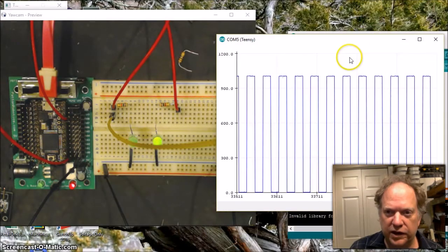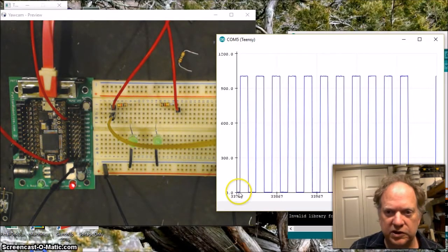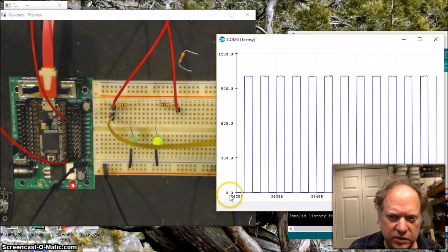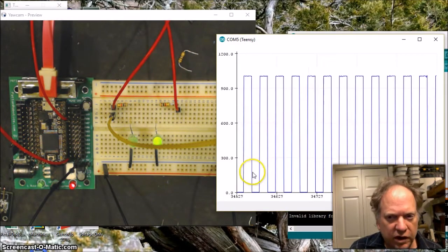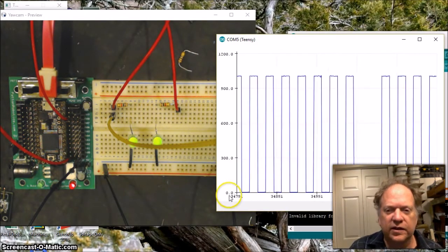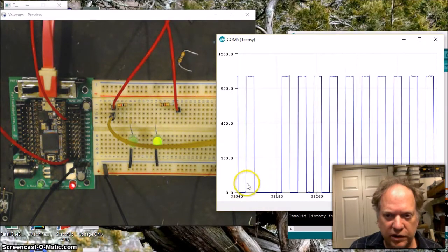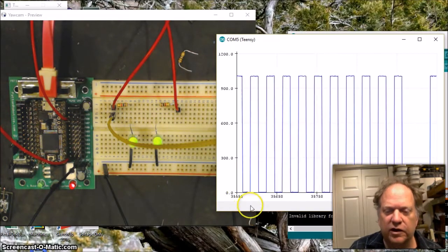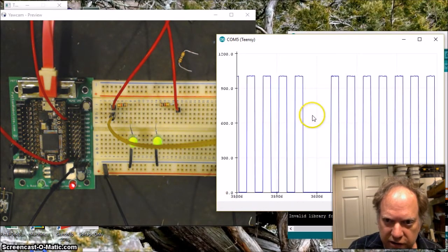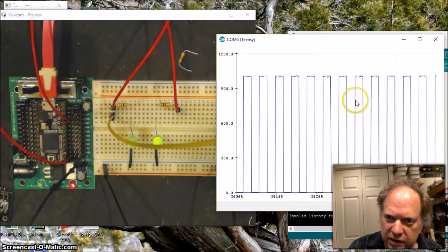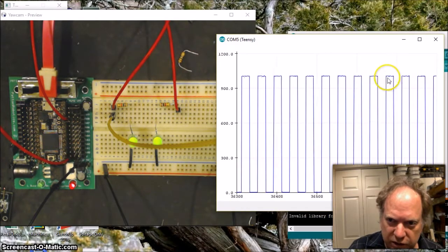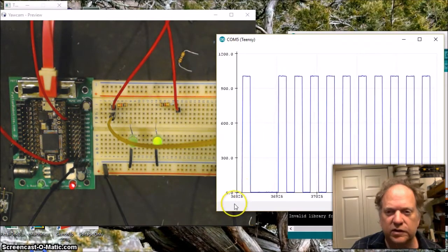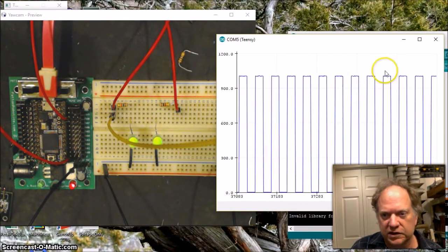So, the way they do that is with pulse width modulation. We send pulses out that will turn the motor on briefly and then turn off, and turn on, turn off, turn on and turn off. That is actually the way we get a nice line going up, okay? Because right now it's just on or off. I want to be able to generate a nice line of voltage. I want to be able to make a line going from 0 to 3.3 volts, or in the case of my car, 0 to 72 volts, and be able to adjust the speed of the motor.